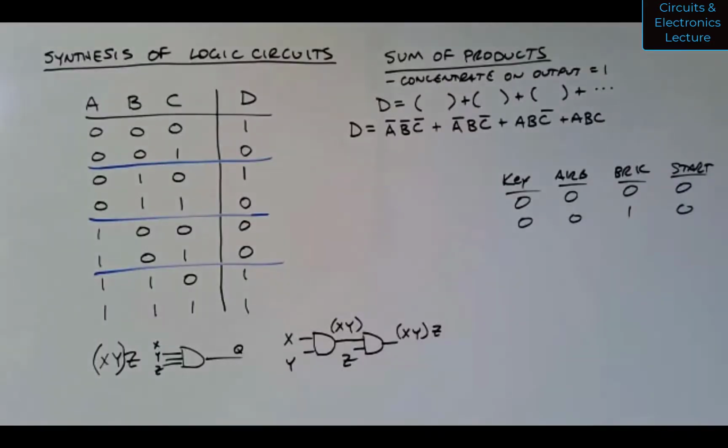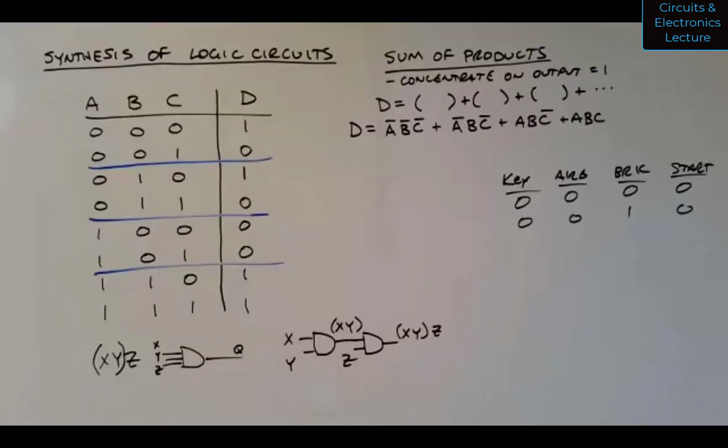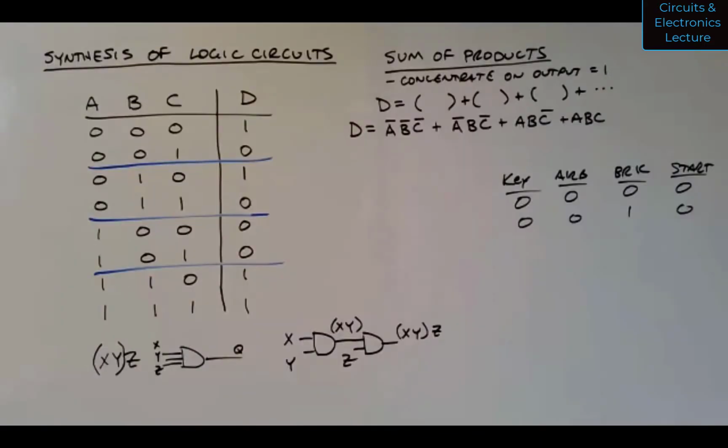Do they use these in 7-segment displays? Yeah, you could actually create a logical circuit to go from a binary number to a 7-segment display. You need to go up to 9, so you'd need a 4-bit number. You can map that to whether each individual segment of the display would be on or off.